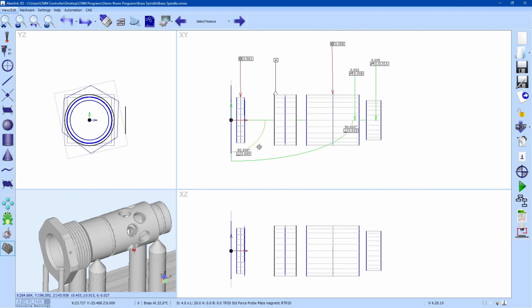If you look at these two, this one, just using the front face as a reference, is 90.2 degrees, whereas the larger bore is 90. When we dimension this one first, it's aligning through here and checking out the YZ positional error essentially to this circle, aligned through this plane. And if we do it the other way, because this is skewed, when this sort of squares itself up, this will be way further out, which is producing the much bigger concentricity error.